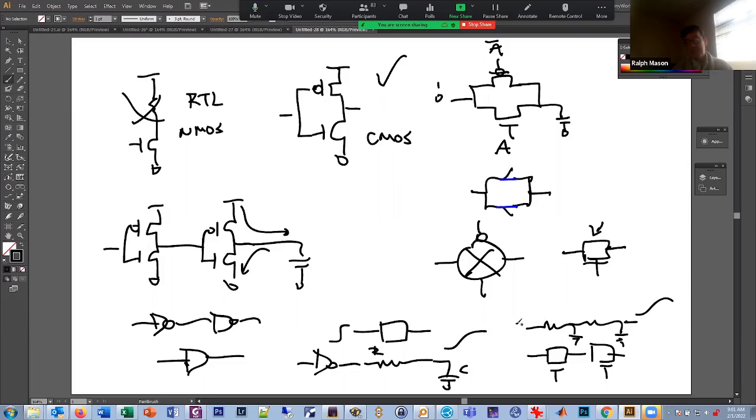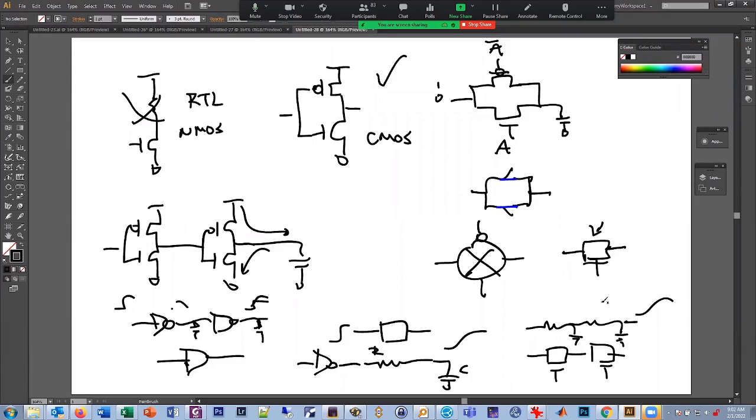Whereas if you make inverters, every time it's drawing capacitance, it's okay because this was a sharp signal. There might be a little bit of delay, but then it gets squared up again. So the delays never cascade when you have a bunch of CMOS gates in series, whereas transmission gates, they do. Okay, cool.